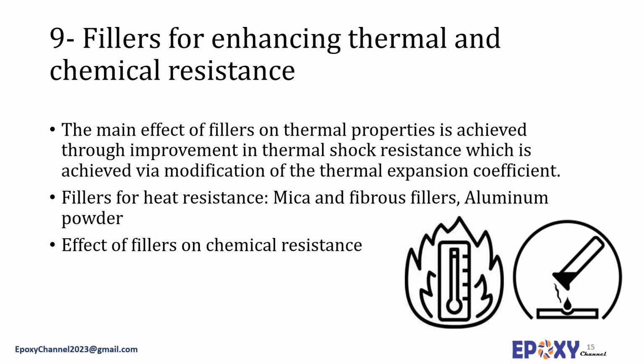And this is particularly true for high surface energy glass fibers, and especially when the fibers are exposed, such as when the cured epoxy is machined or a crack is formed in the adhesive resin matrix. For this reason, glass fibers that are used in adhesives are often treated with a coupling agent such as an organosilane to improve the bond between the fiber and the epoxy matrix.